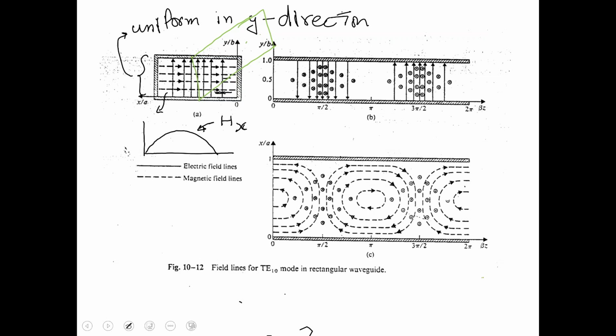Basically, you now have the e^(-jβz) term showing up, which effectively is a term which is cos(ωt − βz). Remember, whenever we were doing these solutions, we had assumed that the fields were going as e^(jωt).